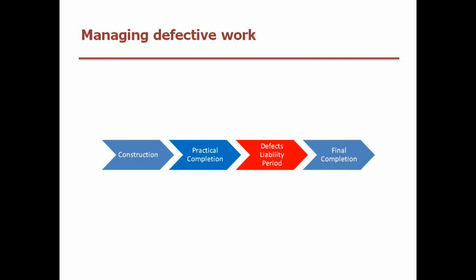Managing defective work is a very important part of getting what you paid for, in the sense that the work achieves the quality standard and the performance standard that was originally asked for. So the defects list, the defects period, the issue associated with maintaining good control measures and reporting measures, inspection measures on defects, and also, if necessary, using the defects list as a tool to potentially withhold monies, might have to be.